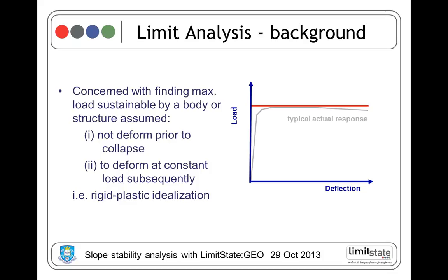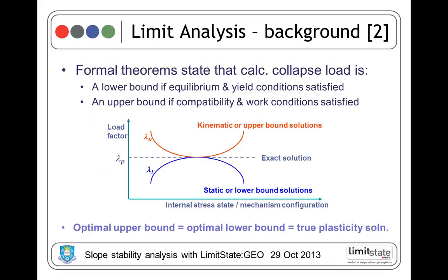Now, the software is based on the limit analysis approach. I'll just give a very brief overview of that. In limit analysis, rather than assuming that the soil behavior perhaps follows this grey curve, which is an elastic phase, then a yield, and then perhaps some post-yield softening, it's assumed to be a rigid plastic material. Therefore it doesn't deform until it hits collapse, and then we travel along this red line. As we get deflection, we just mobilize a constant strength. And this allows us to use some very powerful theorems, which are well known.